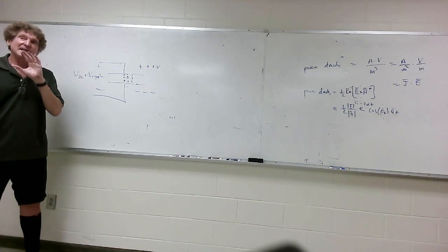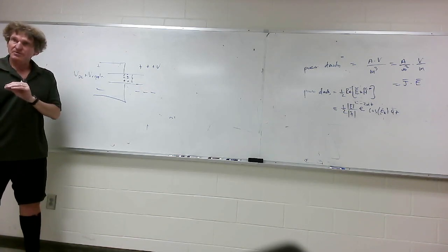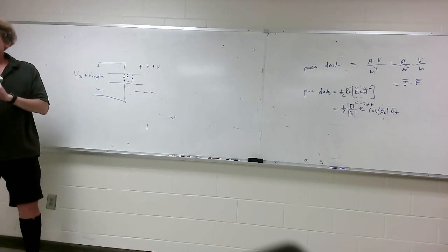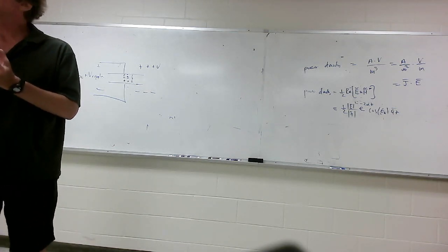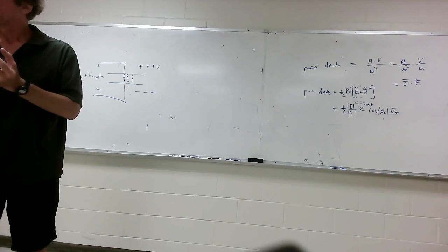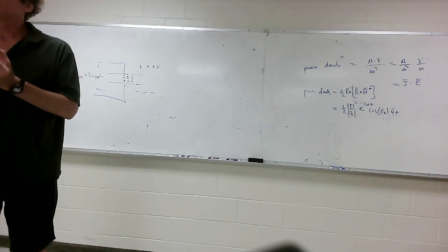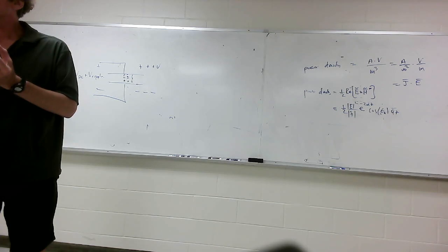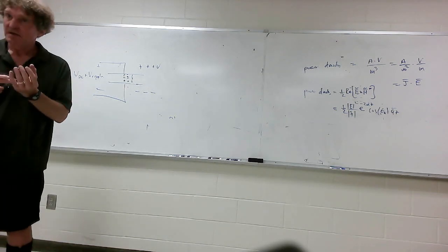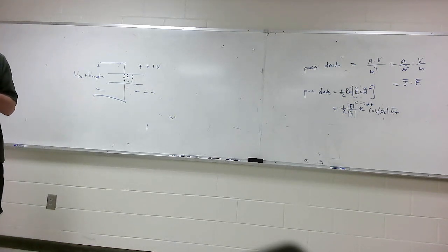There are electrolytic capacitors. Have you heard that term? Electrolytic capacitors are basically things that always assume you have only one polarity of voltage across. And they're used in full wave rectifier circuits, things like that. Or filter circuits where you have DC and a ripple, but you want to get rid of that ripple, so you put these massive capacitors across where the ripple is. Now, they're gooey, and the dipoles can flip. But when they flip, they heat.